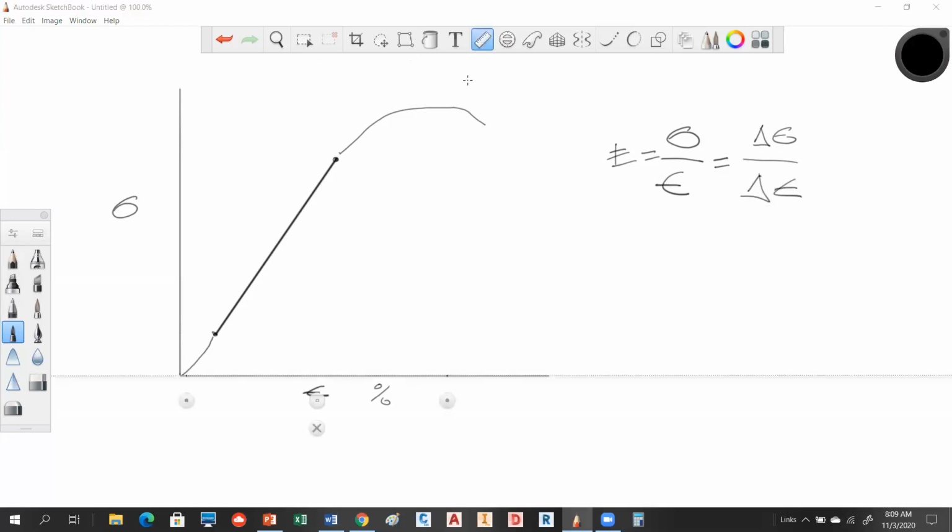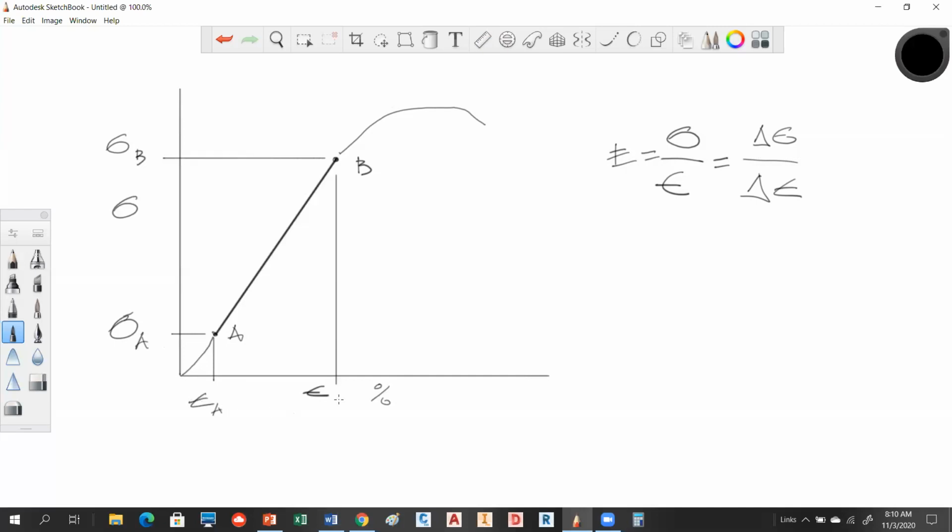So you're going to find 2 points. And you're going to bring this point over here, and you're going to do the same thing down here. And then you're going to do a companion point on the stress or the strain point. So you're going to come down here, and you should probably draw these 2 points on your graph, just like I'm doing it, so you can read them, okay? So if I call this point A and point B, over here I will have a stress B and a stress A, and here I'll have a strain A and a strain B value, okay?